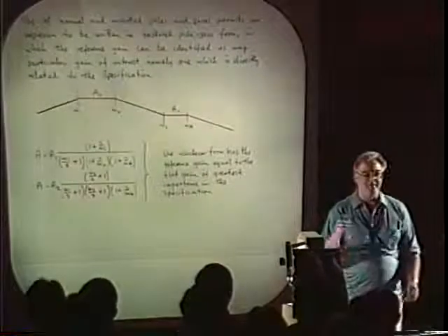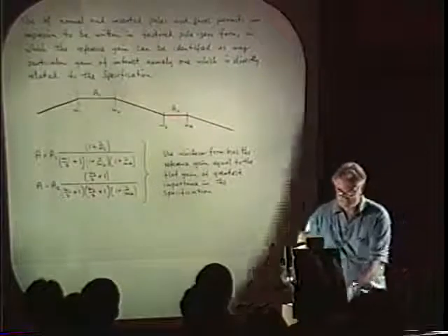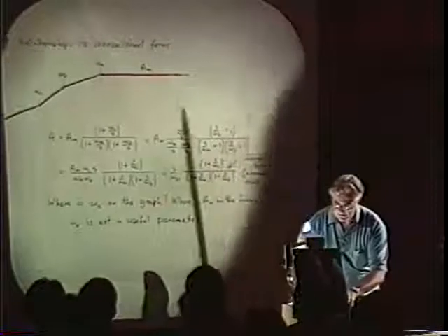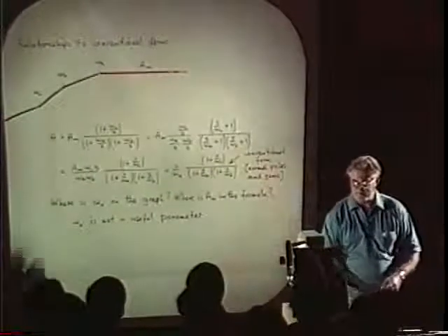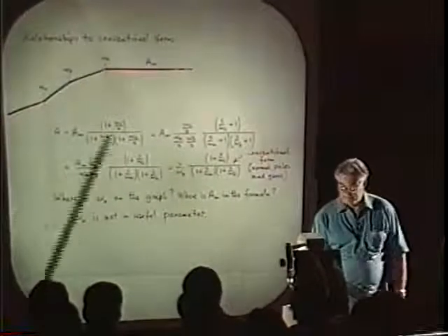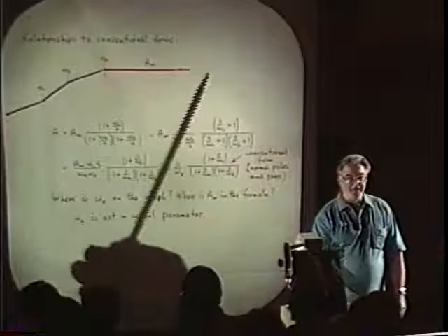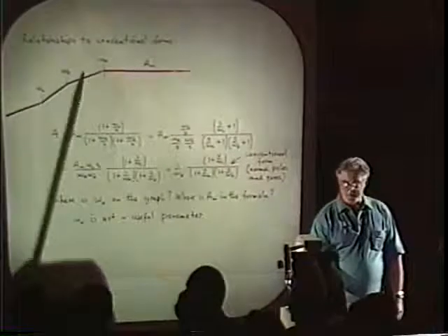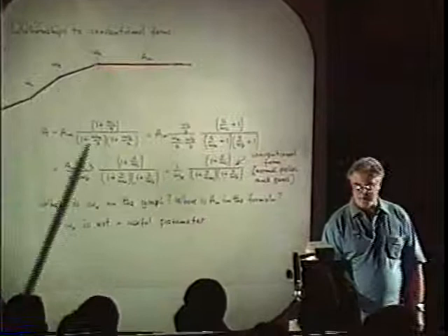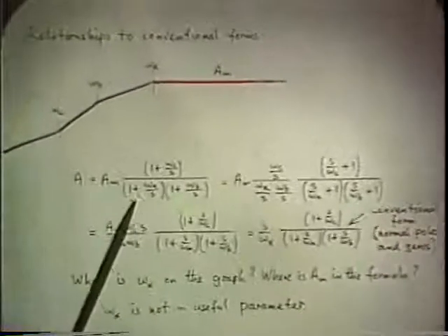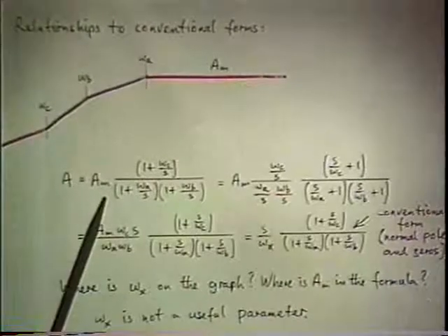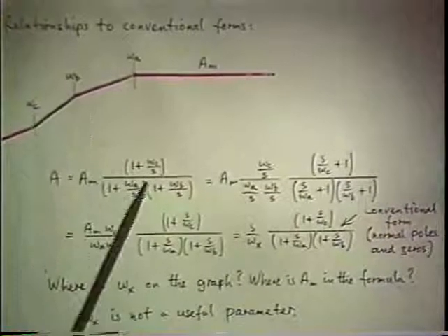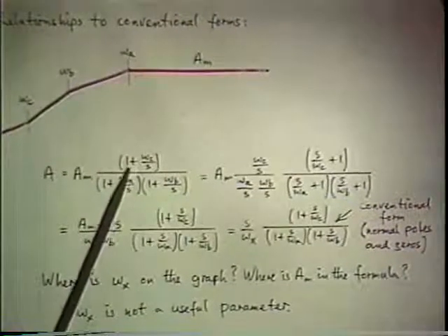And just to hammer that home once more, here's a slightly more complicated example. The flat gain is at infinite frequency, so representation of the three corners in inverted form is what I would recommend. So there's two inverted poles and one inverted zero.